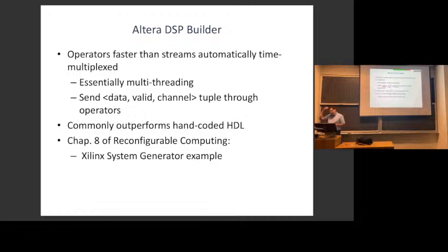Usually when you go to high-level synthesis, you don't put your clocks in, you don't write your Verilog, you get your job done faster, but the resulting hardware is not as efficient. In this case, because the input block diagram is from a certain domain, signal processing, it's feed forward, without a whole bunch of loops in it. It's mapped to this streaming data flow that is known to be very efficient for that. The tool automatically pipelines and retimes and actually outperforms what the typical human can do. But that's basically because it's specialized to a certain domain. It knows a lot about the kind of hardware that is efficient for this, and that makes it easier.